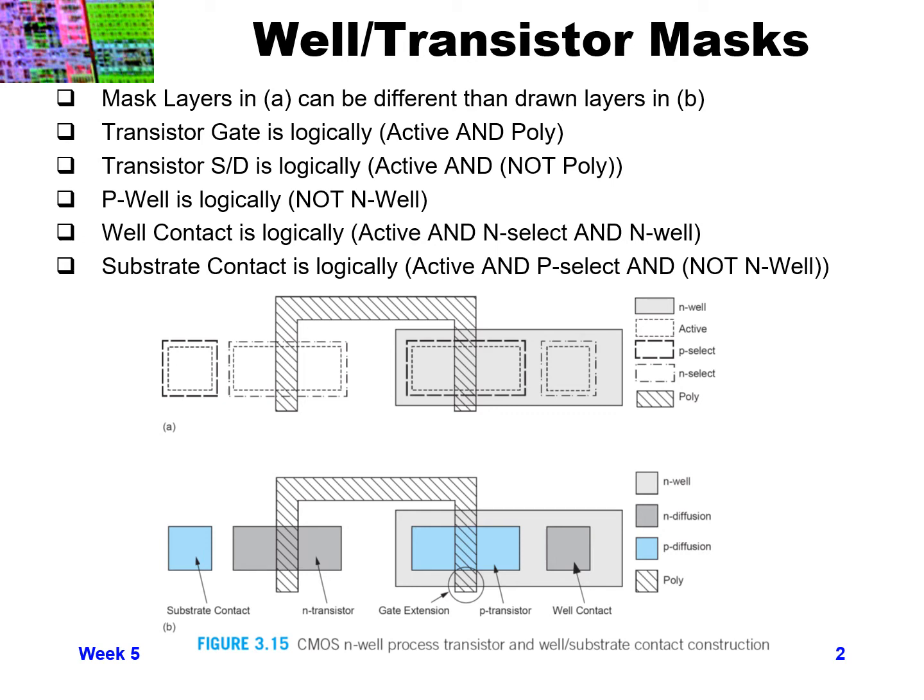So you're drawing 4 layers, whereas the actual masks that will get created are an N-well mask, but instead of N-diffusion and P-diffusion mask layers, you'll generate an active layer and then a P-select layer and an N-select layer. And so there's not always a one-to-one correspondence with what you're drawing in your layout tool and the mask layers that get generated.